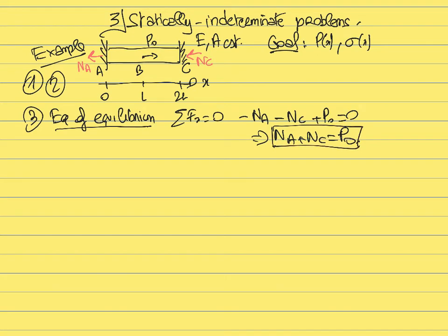Now we can write that the sum of the forces along y equals 0, but in this case there are no forces along y, so we cannot learn anything from this. We can also write that the sum of the moments is equal to 0, and we should choose the point through which most of the forces have a line of action going.